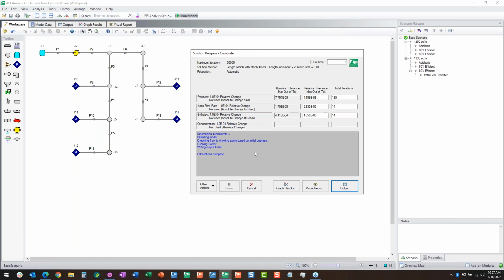Sometimes this could lead to really long run times, especially if you have a lot of control valves, because it might be going through and one control valve can't control, it has to start the whole thing over, and it goes through again, another control valve can't control. It starts over again, and so it was not immediately clear that this was happening when you're just looking at the solution progress, that the control valve states are changing, and that's why you're having a very long runtime. Now we'll show that here in this blue text.